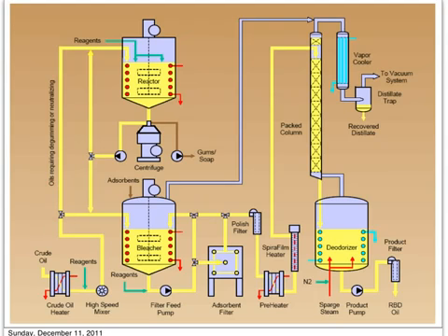In a chemical refining process, the next step would be the neutralization process, where sodium hydroxide, the alkali, will be added, and this will react with the free fatty acids, and the gums will be formed here. So we have the oil and the gums together, formed during the neutralization process. We need a centrifuge to separate the oil from the gums, or from the soap.